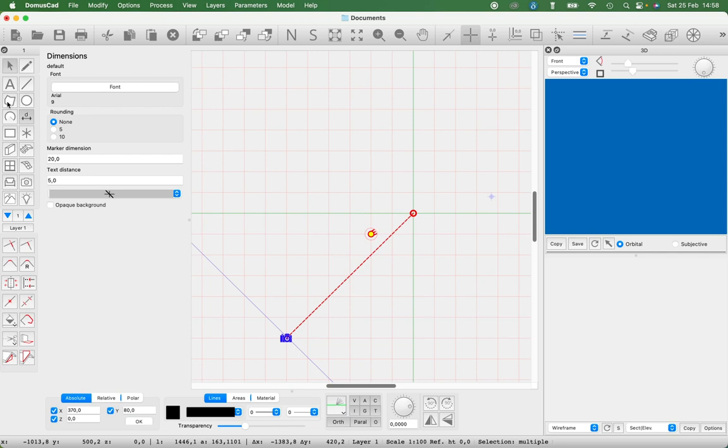Dimensions are entered by clicking in succession on a series of points. Click in the center of the arc and trace the radius until pressing enter or the space bar. Then move the mouse and click at the end of the arc until a subsequent mouse click.